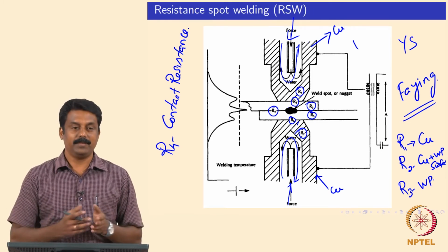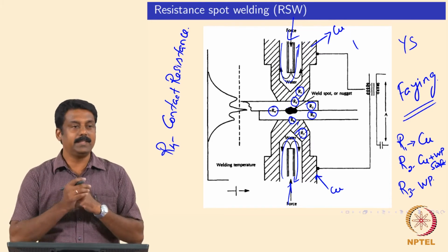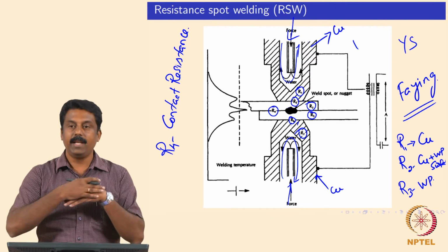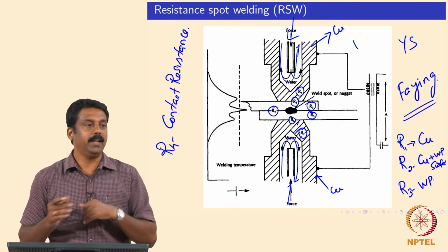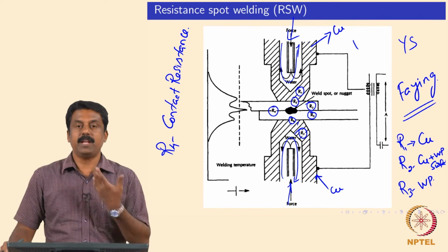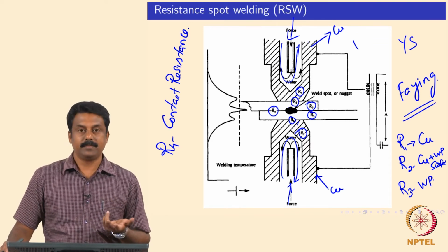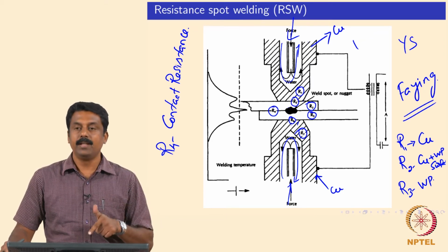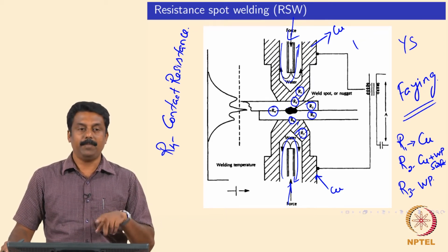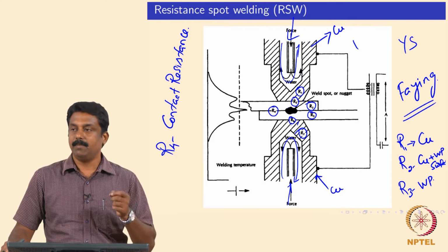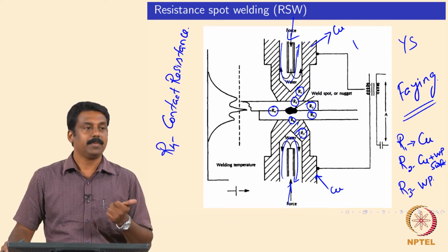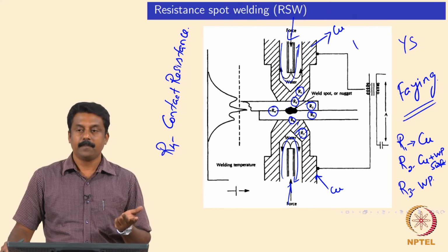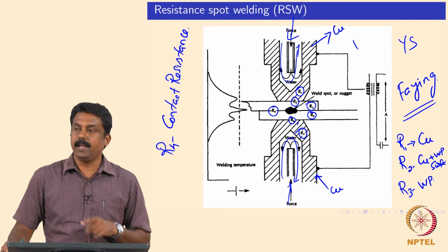So, obviously 2 kilonewton, because when you increase the load, you also plastically deform and reduce the surface roughness. So, you are bringing the surfaces close to each other, right. So, you change the load, you also change the contact resistance. So, the contact resistance, in other words, the heat generation, is a function of various parameters, which involves the material surface roughness, material surface conditions, the load you apply, okay, and then that will determine the heat generation.